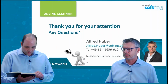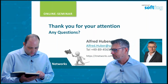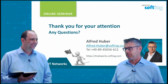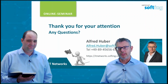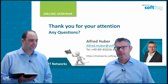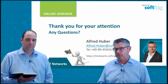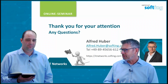And one more question which I didn't answer until now. What is the best way to clean the end face? It depends on the dirt or on the situation you have. So the best way is to see what the problem is. The easiest way is to use the one-click cleaners, definitely. If it doesn't go away, you use some liquid and some proper tissues, not the tissue you use for other things. So use proper material for cleaning. It depends on what you see.